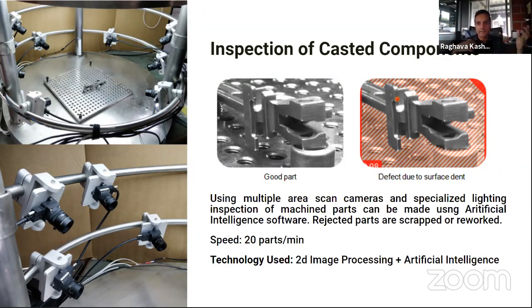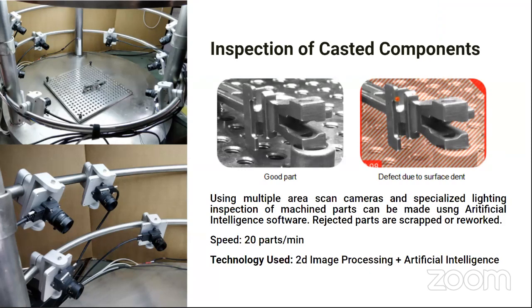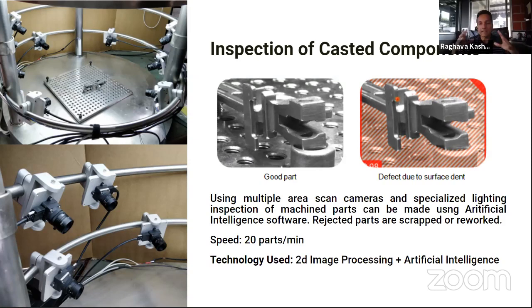Our project engineers program this workflow to collect the data. It identifies which variant is running, and there may be 7 different variants in that plant for a given part. You can configure that you need 100 OK samples of this variant, maybe 10 defective samples of another variant, and you need it over 4 days. Once you install the camera and deploy it, using maybe a barcode reader, the control system will tell you which variant is running, and that is usually predetermined. You need 100 samples of all those different variants.